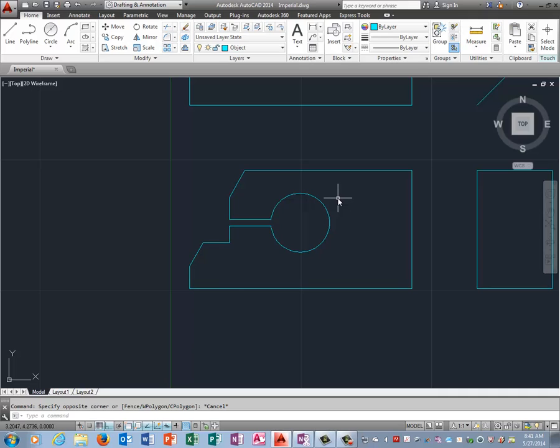And it tells me that this angle starts 1.94 over. So I'm going to offset 1.94. Okay, and now I'm going to draw this angle. Click on line, click there, shift comma, and it's going to be negative 34 because it's 34 degrees below the horizontal. Okay, and then we trim.